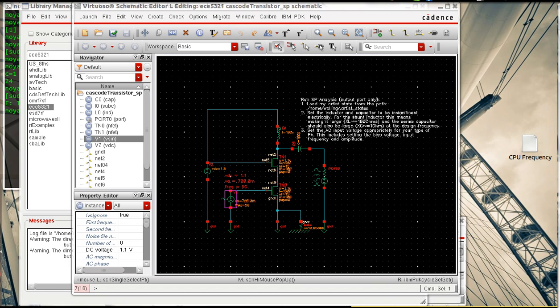Let's examine the voltage source. We've placed a DC voltage source on the signal that's equal to half the difference between the peak voltage allowed, 1.8 volts, and the threshold voltage of 0.4 volts. We've also set an amplitude of 700 millivolts for the sinusoidal signal and set a frequency of 5 gigahertz. This isn't important for a standard S parameter simulation, but for a large signal S parameter simulation, or a PSP simulation, we need to have this information. S parameter simulations are small signal and are agnostic to any amplitude or DC settings of the signal.